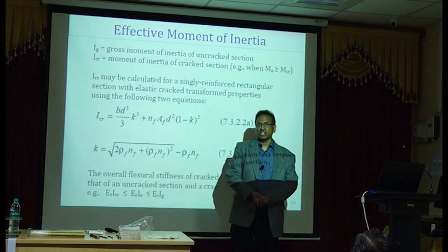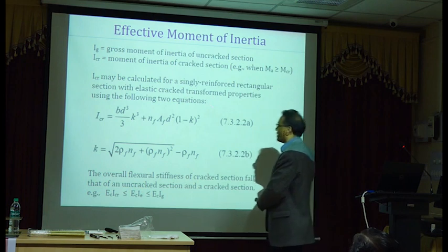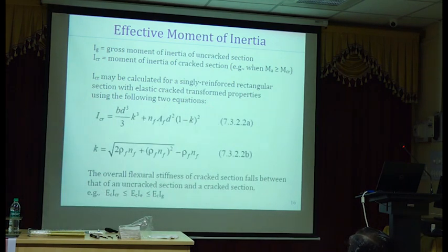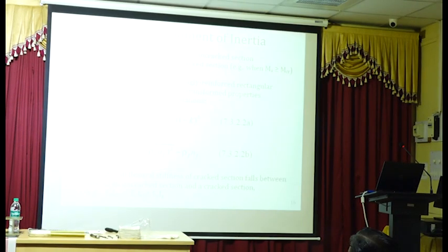n_f is the modular ratio. What is the modular ratio? n_f is equal to E_f over E_c. E_f is the modulus of FRP, E_c is the modulus of concrete.